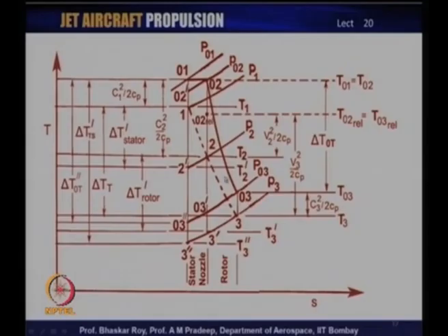And then of course, it comes through the rotor to T 3, where the work is actually performed, and it is down here at 3. It is at a different pressure. It has lost a lot of pressure in the process of doing work. It has also lost a lot of temperature in the process of doing work. So, a lot of pressure and temperature potential energy has been given up in the process of doing the work, and then this work of course shows up in the form of temperature differential delta T 0 total, and this is the work that is being done by this turbine in the process of drop in this temperature.